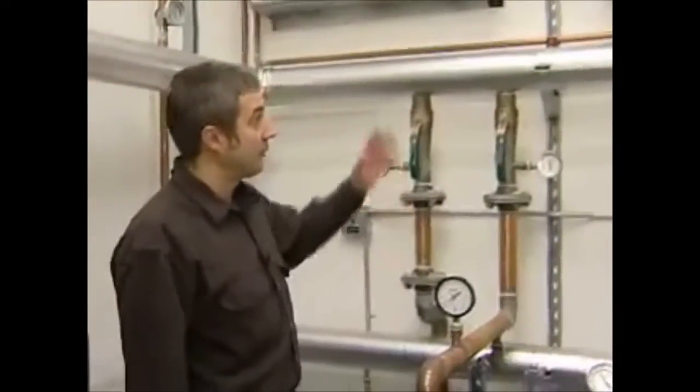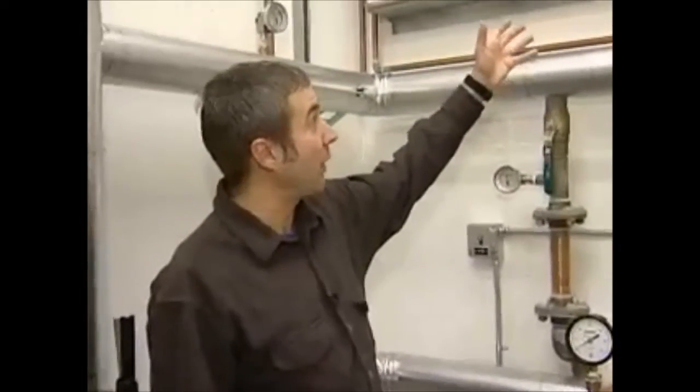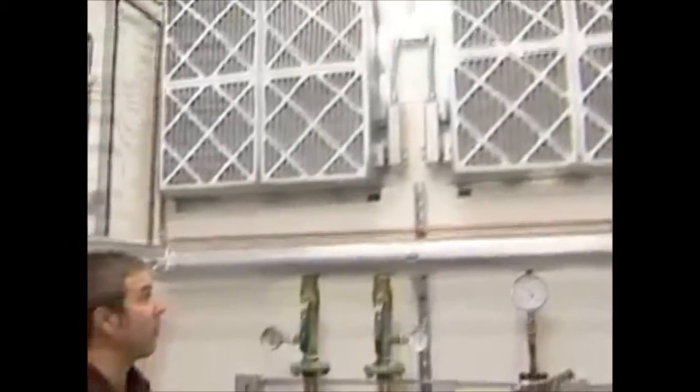Associated with each radiator is an air intake damper. Same thing, the duct through the wall has a motorized damper on it. When the radiator operates, this damper opens to allow fresh air to come in for cooling of the radiator. And we've installed filters on these intakes that cut down on the bugs and the dust that's brought into the room. Now the radiators are controlled by a variable speed drive.